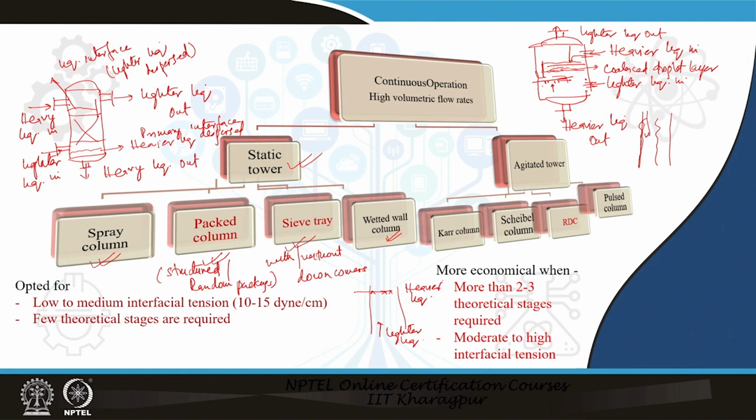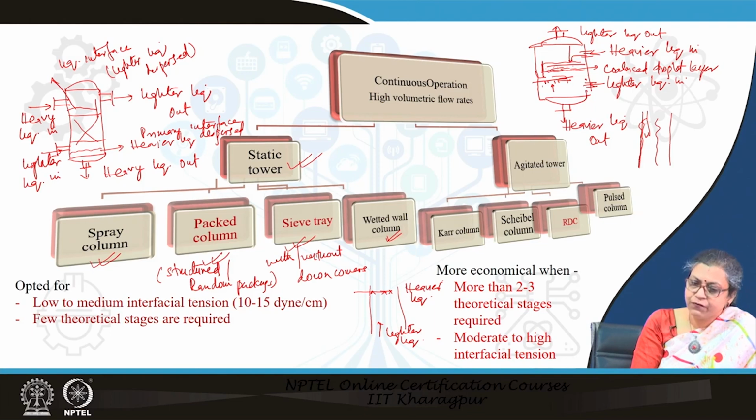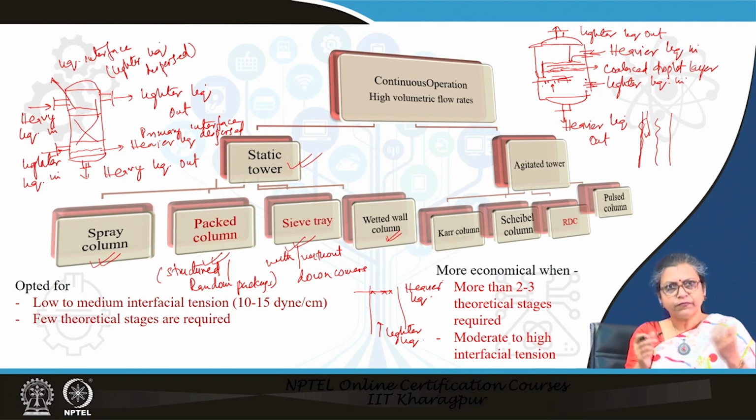Now, let me tell you one thing, that very frequently when we are going for continuous operation for liquid-liquid extractors, we find that we need a large number of theoretical stages. Why? Because in order to bring about the mass transfer, a very large number of theoretical stages are required, and it can also happen that it is comparatively difficult to disperse the liquids due to their higher interfacial tension.